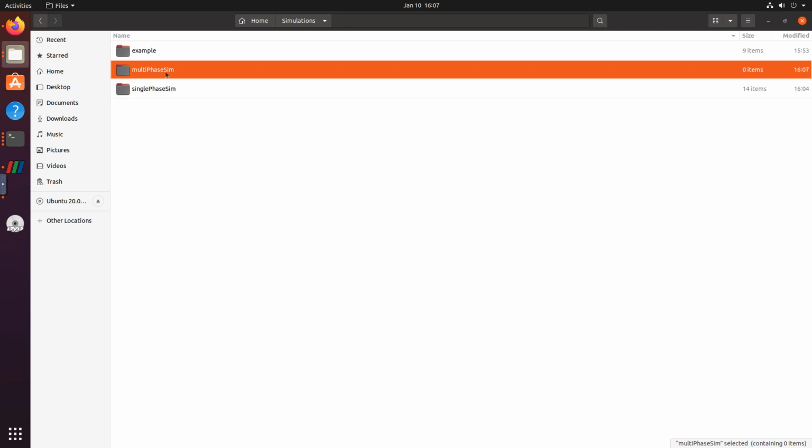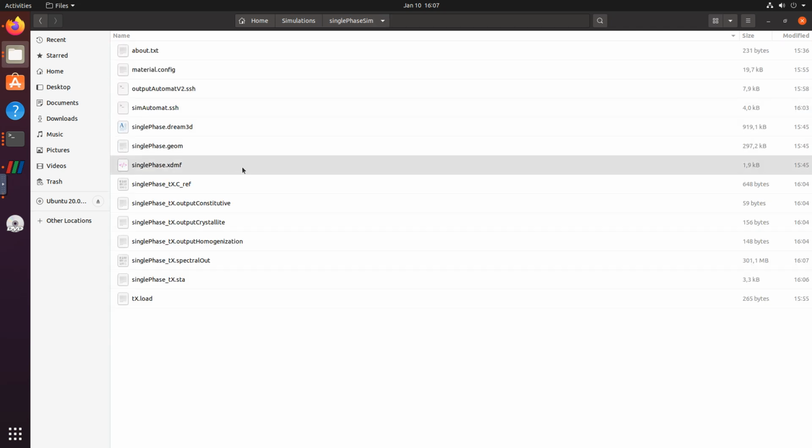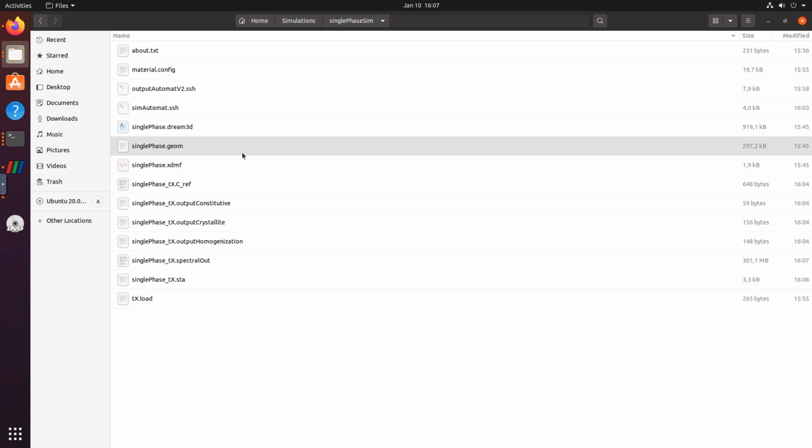Okay, and in this case, what I basically want to do is I want to change two things. In this first case, we just had ferrite matrix, or all the grains were just one single material, ferrite. In the second case, I want to copy this file and I want to manually change some of these grains to, let's say, martensite. Okay, just to give you an idea, to repeat what we discussed in the past, how DAMASK reads files and information, and then how we can alter these files.